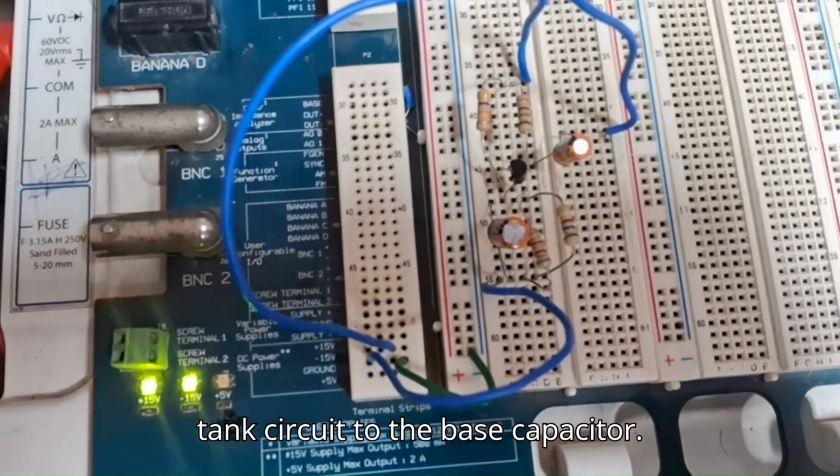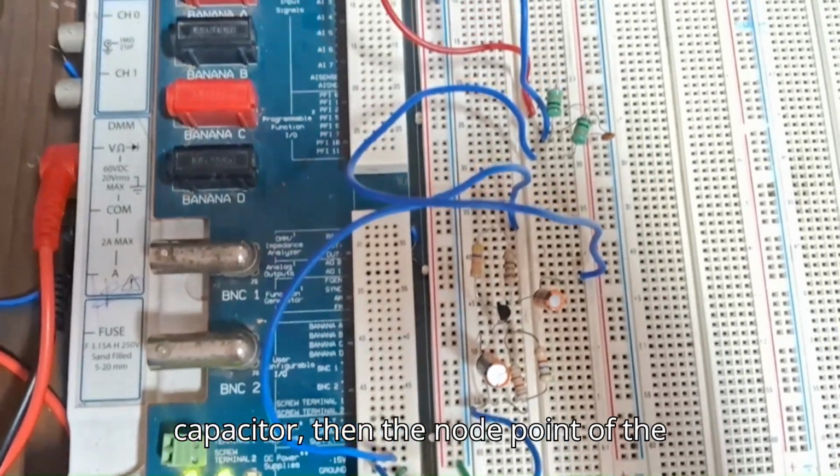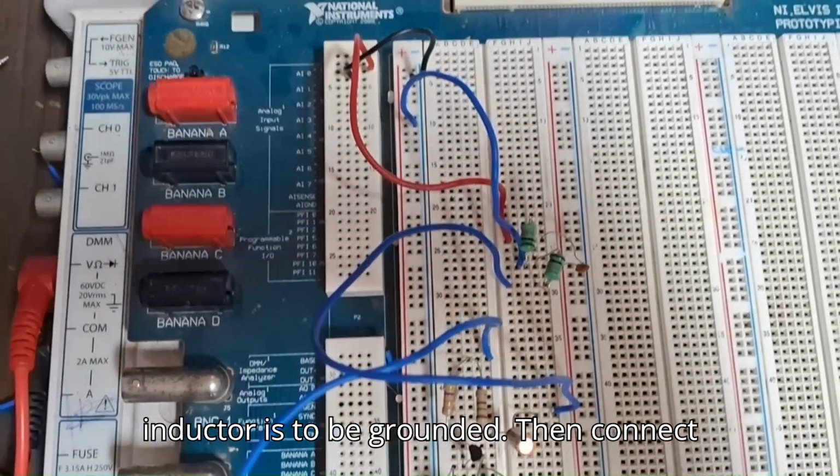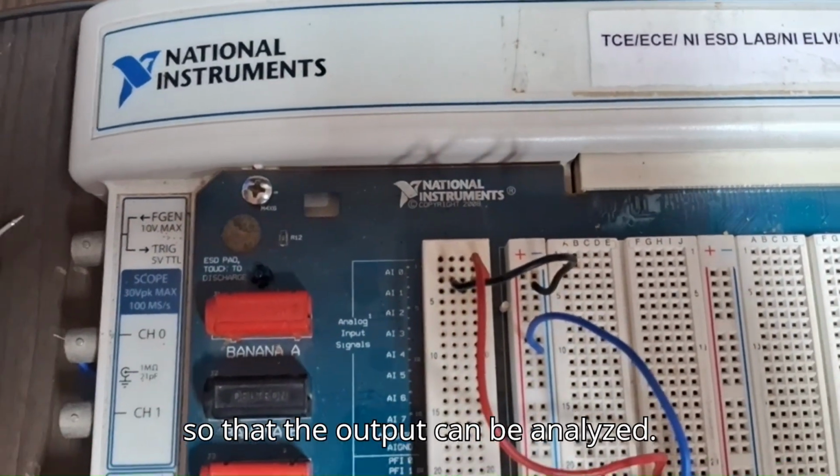Connect one end of the tank circuit to the base capacitor. Connect the other end to the collector capacitor. Then the node point of the inductors is to be grounded. Then connect the output capacitor to the oscilloscope so that the output can be analyzed.